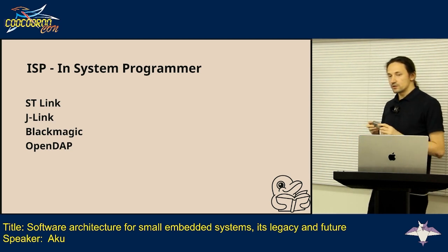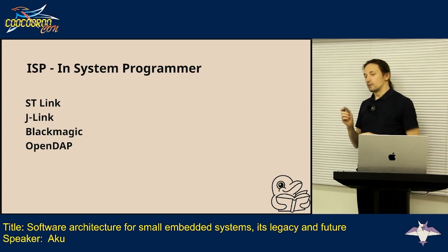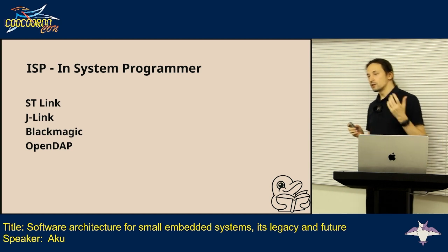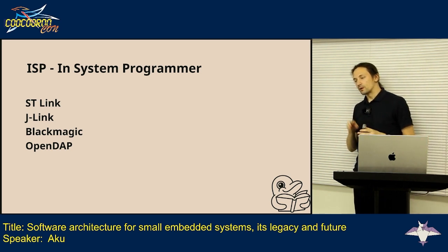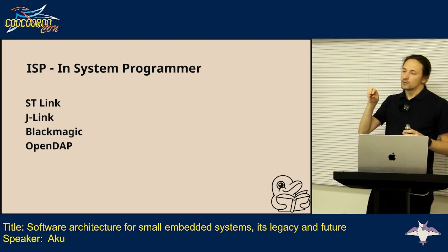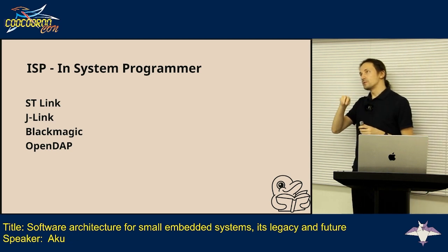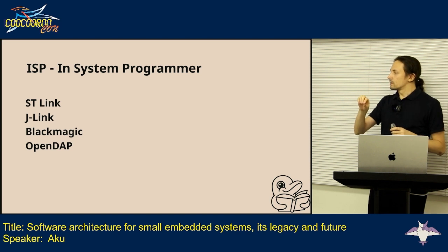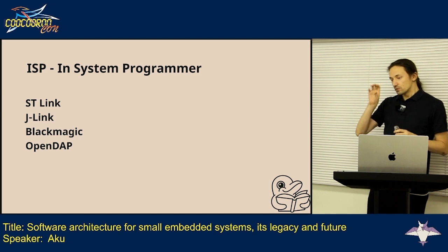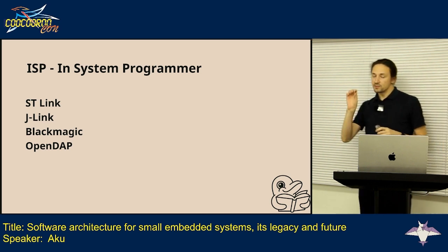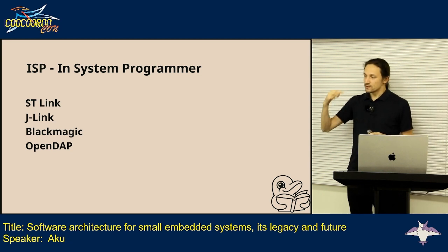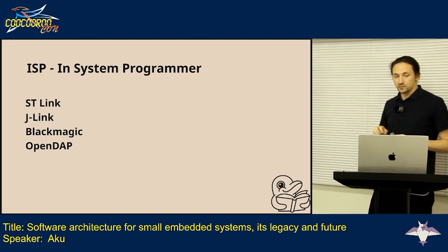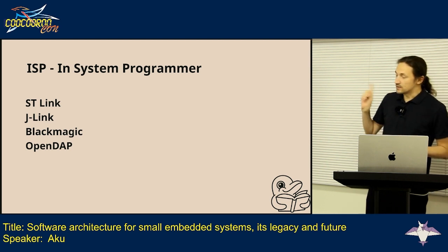So usually each microcontroller has its own special debugging port. It's either JTAG or SWD or some other transport that basically gives you control over the computing core itself. It allows you to define when exactly, let's say you want to stop at some specific instruction at some specific place. You just program through the DAP a specific address, and that's where the microcontroller automatically stops when reaching this instruction. And that's why you need an in-system programmer.